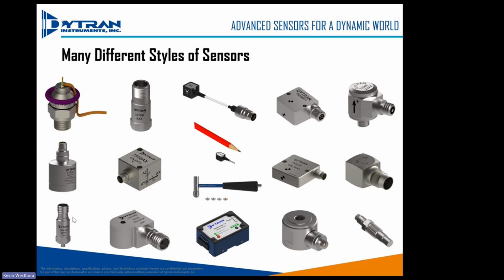Where this seismic accelerometer on the far left, excuse me, has a natural frequency of 2 kilohertz and a usable frequency of about 500 hertz. So the upper level frequency of an accelerometer is limited by the design of the sensor, the mass, the connector, the cable, etc. That determines the upper frequency limitation.